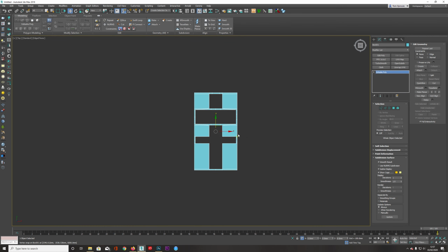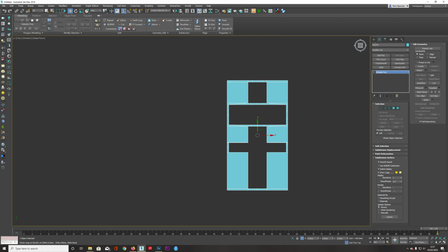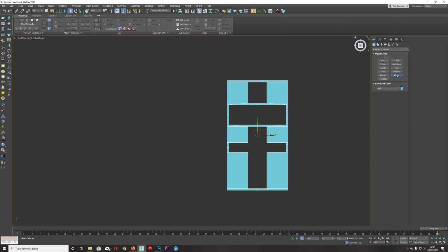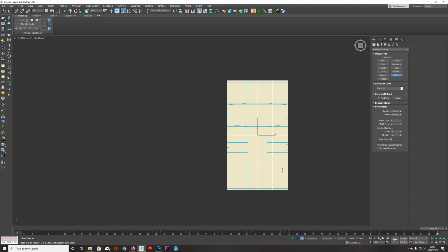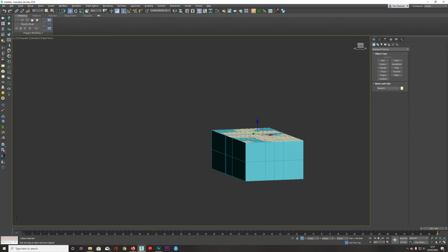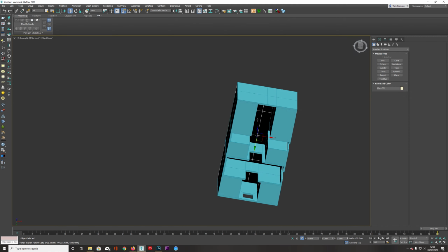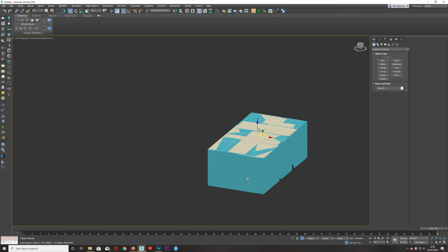So I'm going to go top view, and rename this to walls. Then I'm going to click on standard primitives, click on plane, with snap enabled, making sure it's snapping to vertices. Come near this so you can see that yellow cross, snapping to that vert up there, and drag this down to this one. Right click, and that's the roof, but we've got back faces here, that's why it's dark from the bottom.